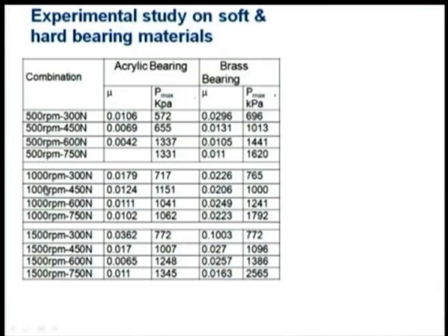Now, if we increase the speed from 500 to 1000, pressure is increasing, which is clear. In hydrodynamic bearing cases, an increase in speed will increase the maximum pressure value and the load carrying capacity, and the pressure profile changes to a much lesser extent. So, in this situation, it is slowly increasing and then subsequently decreasing in the elastic deformation case. Now, this is interesting to note.